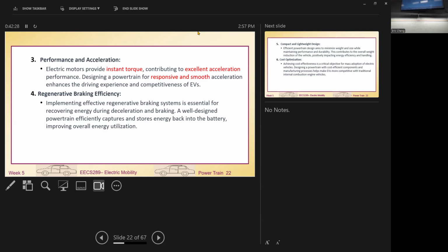Usually the total added together cannot be more than 180% efficiency. So if you have 90% there, then you may have less than 90% in the power regeneration. Sometimes it may only go down to 70% or 80%. So that means adding both together, we have difficulty having high efficiency at both ends because you can't design the motor perfectly.